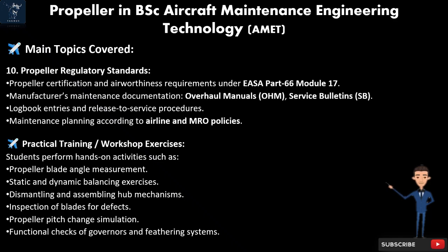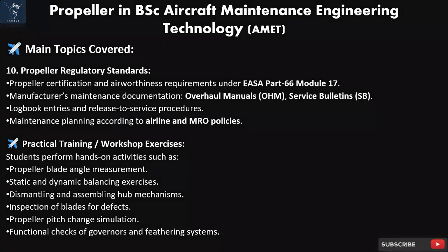Airplane practical training/workshop exercises. Students perform hands-on activities such as propeller blade angle measurement, static and dynamic balancing exercises, dismantling and assembling hub mechanisms, inspection of blades for defects, propeller pitch change simulation, functional checks of governors and feathering systems.